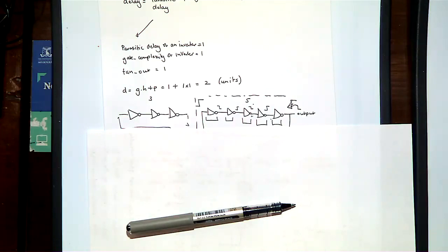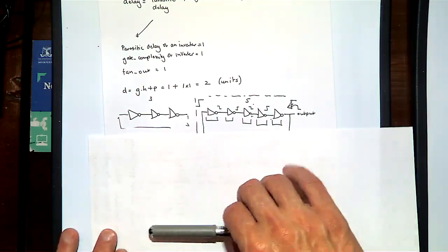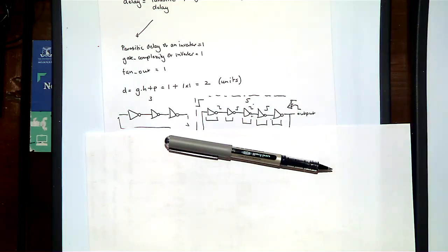So yes, it depends on mobility, it depends on a whole bunch of things, right? It depends on the doping of your wafer. And usually what you do, if you want to work out your particular process, is this. I don't imagine you've seen this before, but when you're producing chips on a wafer, some areas get more doping than others, right? So at the center, where you're doing implantation, there's more phosphorus, more boron, so the transistors are going to operate faster there, and towards the edges they're going to operate a little bit slower.